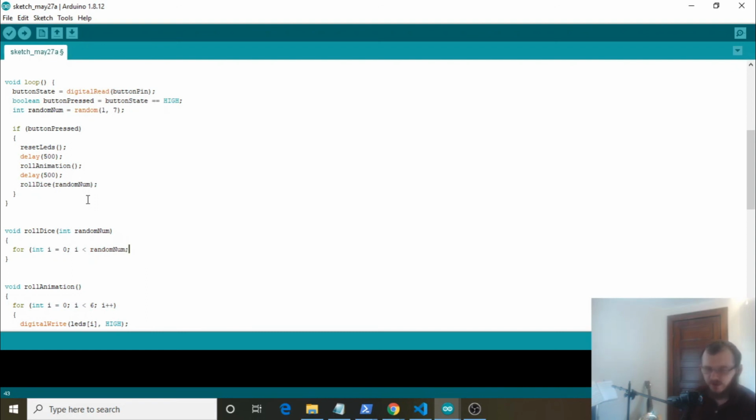Okay, so the random number is somewhere between 1 and 6, we said, right? i plus plus. And we're going to get to what this does in just a second. digitalWrite, LEDs, i, HIGH. So we're going to turn on however many LEDs, or X amount of LEDs, up to the random number.